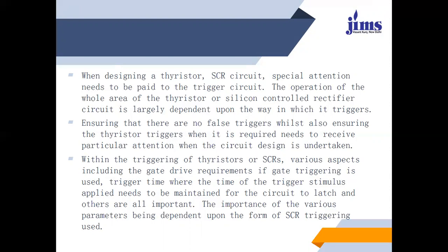Within the triggering of thyristors or SCRs, various aspects are important, including the gate drive requirement if gate triggering is used, and the trigger time, where the trigger stimulus applied needs to be maintained for the circuit to latch. The importance of the various parameters depends upon the form of SCR triggering used.